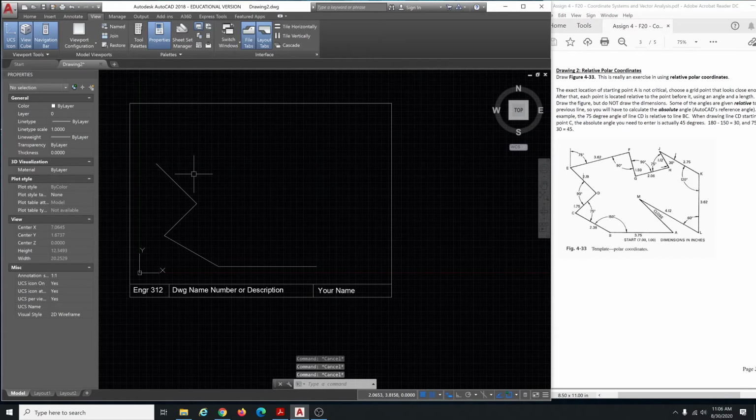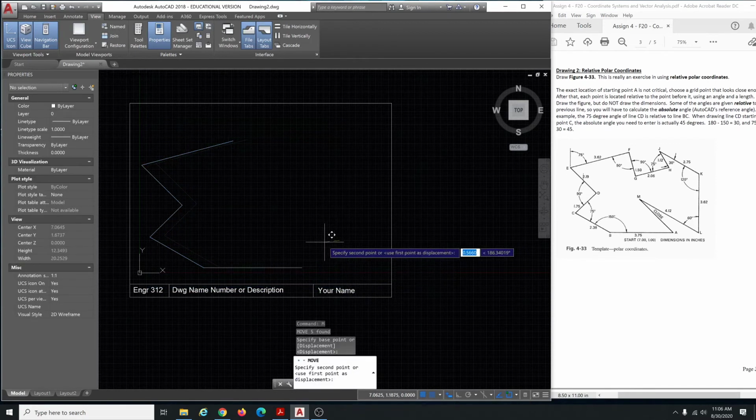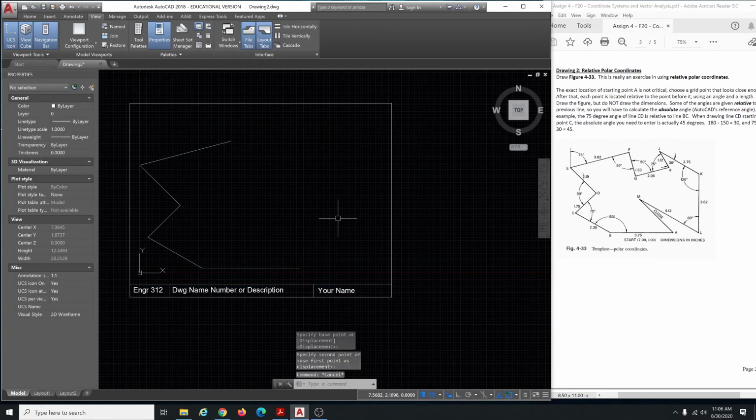escape, it was getting stuck, so I pressed escape. L, enter. Now you get a box, that's endpoint snap. So click, then I'm trying to do 3.62, tab 15 degrees, enter. Okay, go on around like that, get this guy finished. If you run out of room, you could grab everything and move it a little bit. It's not a big deal.